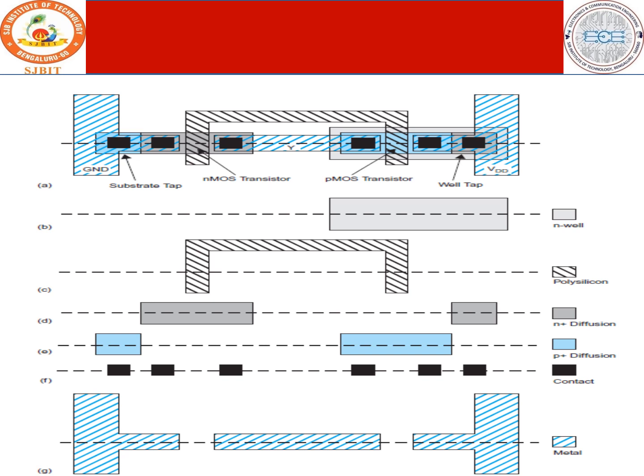And the first type of mask: how basically we start with the substrate. After the substrate, the first and foremost step is to create a well structure. What type of well are we creating in the p-type substrate? The type of well we are creating is the N-well structure. So create a mask which is called the N-well mask. I hope I am clear. So this is the structure which is called the N-well mask. So when you see this kind of a structure, apart from this area, the rest all N-well is created. So this is your N-well mask.